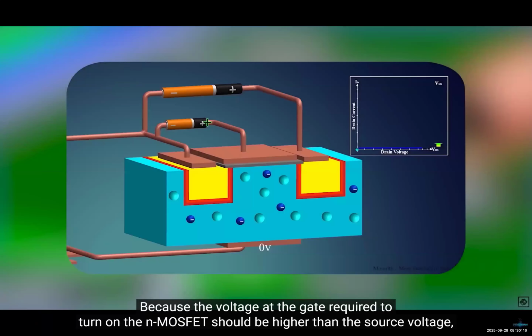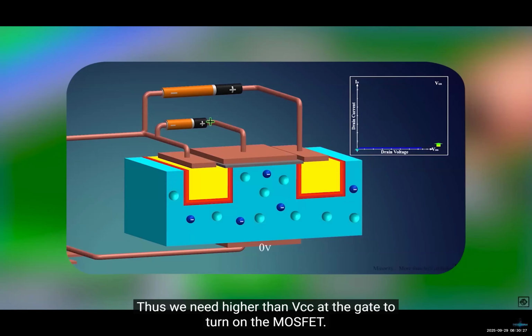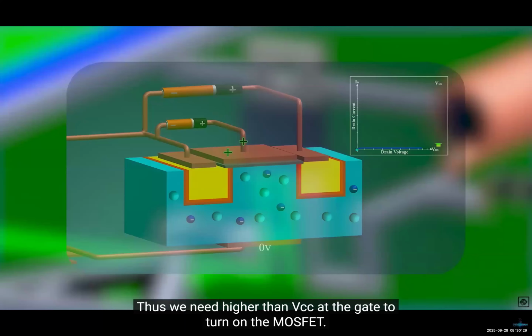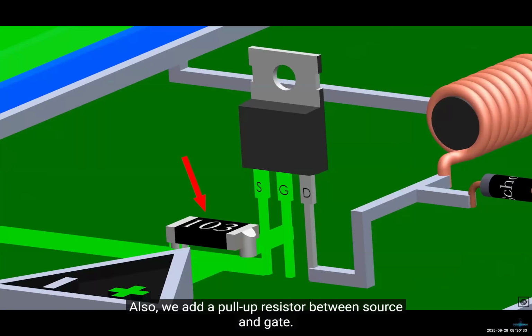Because the voltage at the gate required to turn on the N MOSFET should be higher than the source voltage, and during operation, the drain and source voltage will be almost the same. Thus, we need higher than VCC at the gate to turn on the MOSFET. Hence, we use a P MOSFET. Also, we add a pull-up resistor between source and gate.